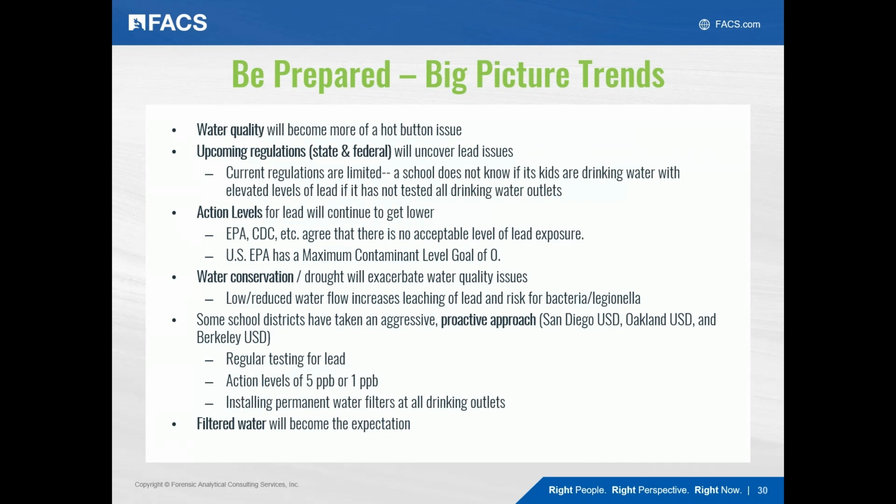And then there are already school districts that are leading the way with very proactive lead programs. San Diego Unified, Oakland Unified, and Berkeley school districts are some examples. They are already incorporating things like regular testing for lead, action levels of 5 parts per billion or even 1 part per billion. Or they have gone ahead and installed permanent water filters at all of their drinking water outlets. So eventually, we predict that filtered water will become the expectation from people.